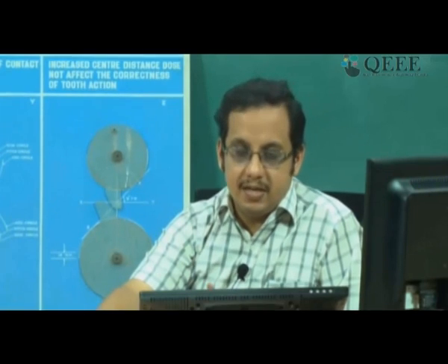So what we will do now is apply this limiting condition mathematically to the minimum teeth criterion, and we will straight away get our rule for the minimum number of teeth that must be present in a gear such that the rack cutting operation can be done in a nice manner without defying the fundamental law of gearing.